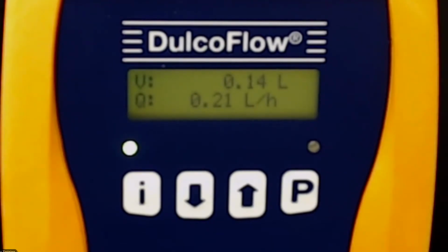What is the viscosity the Dulcoflow can handle? That's a very good question. That I know of, it can go up to about 200 centipoise. I'll try to verify that for you, John. But it doesn't handle highly viscous fluids. It can handle something with some abrasives in it, some larger particles going through it, because there's nothing really blocking the flow going through the device, so it will handle that fairly well. It may miss a stroke count if a particle goes through it.